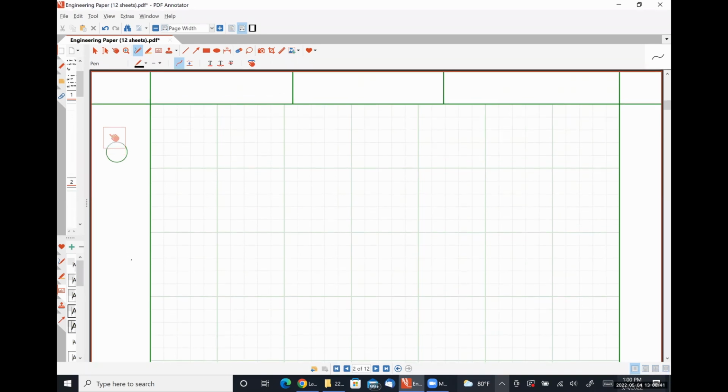So a negative feedback amplifier, in this case, where we're subtracting a portion of the output signal from our source signal XS, what we'll find is that Y, our output, is still A times XI, which is then A times (XS minus XF), or A times (XS minus KY).